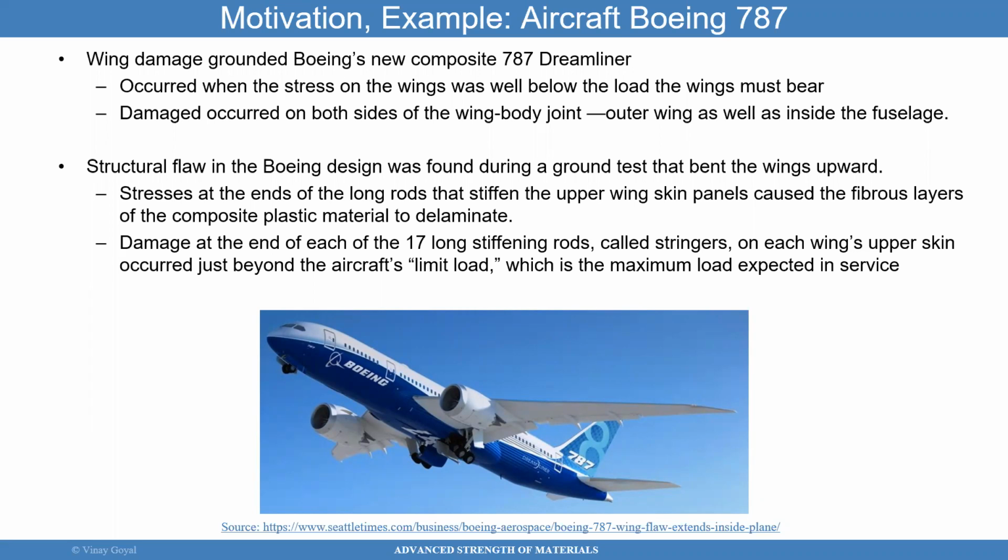Because obviously when you're testing on the ground, you cannot do it exactly as when you fly it, right? The aircraft is on the ground, while when you're flying, it's not, it has no boundary conditions. The air is the boundary condition. It's surrounded by air. It's not clamped in any way. But if I can figure out a way of doing the analysis for the flight condition, I can do it for the ground condition. I can then design a test that's successful. So that's why analysis is so beneficial.